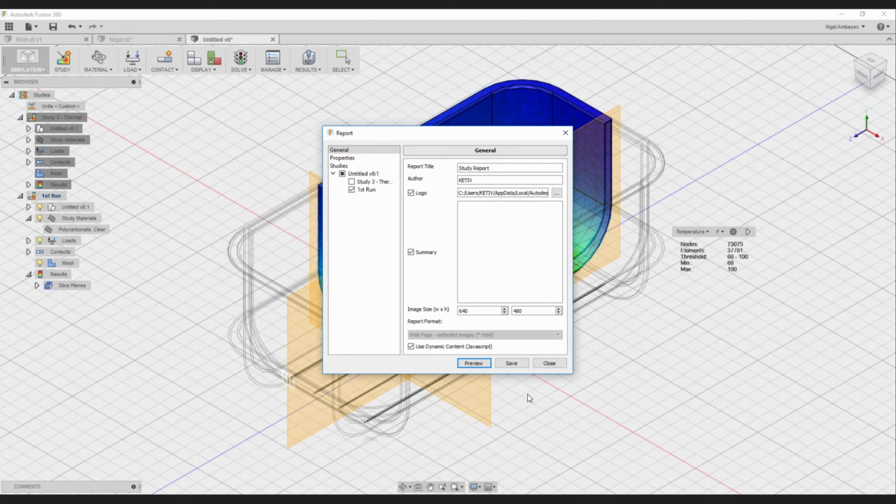We do have a follow-up question from Peter here. So I guess I did answer Peter's question. And the next question would have been CFD. So CFD you can use for full-blown Autodesk CFD. You can use the cloud to do your solving for you. Say you're using multiple millions of elements, like I said before. You use these things called cloud credits to run those simulations in the Autodesk cloud. So your computer is not being taxed. It's going to be the cloud that's being taxed for the computational power. And you don't do that in Fusion 360. Most of the models you're going to use in here aren't going to be millions upon millions of elements unless you've got some kind of supercomputer, I guess.